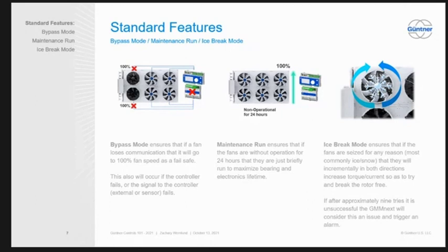If you shut a unit down and don't let it run, the bearings on the fans can flatten. Condensation can also form inside the electrical terminal box and cause damage to the fans.